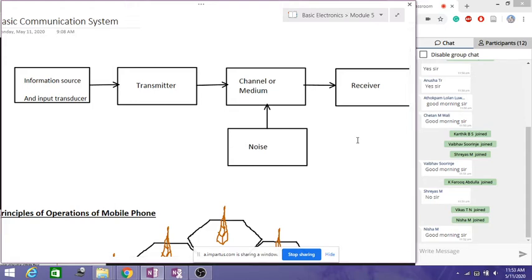If you want to transmit it to a longer distance, we have to perform a sequence of operations on it. For example, take the speech signal which you are listening to right now. To transmit it to your location, I have to convert my speech, my audio signal, which is in analog form, with the help of a microphone into an electrical sinusoidal form. Then from that electrical form, I may transmit it in the same form by modulation, or I can convert it into digital by sampling. Then I can perform digital modulation and transmit through the channel. So there are different methods of transmitting.